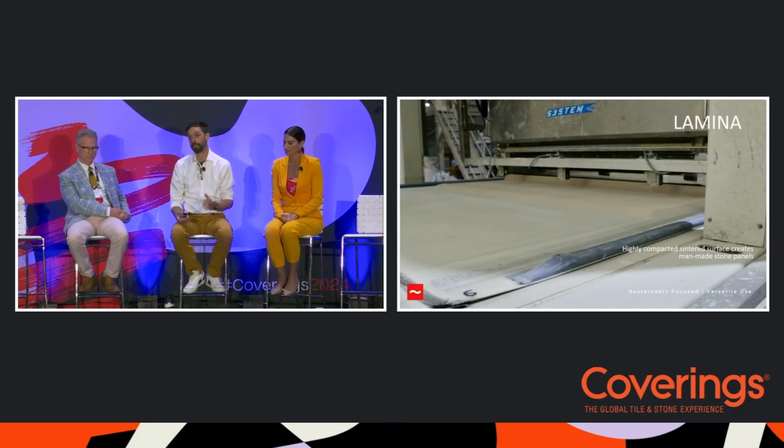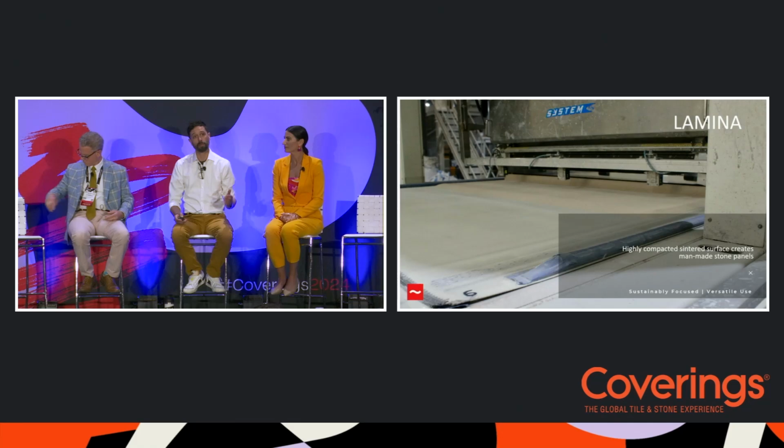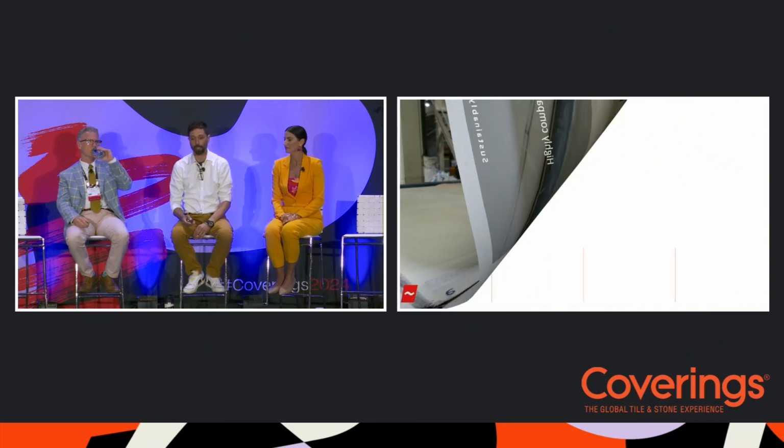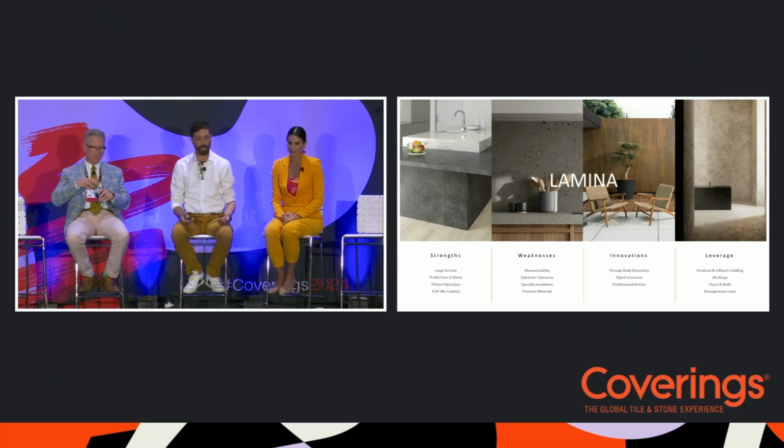And we're going to move on to lamina, which is probably the newest style of production. It's where the gauge porcelain segment comes. It's where our largest formats come. It's very sustainably focused because we do all of our cutting and all of our size gradation before we fire, so any waste material can get reintroduced to the production stream, because as soon as we fire it, it's much harder to reutilize that material.